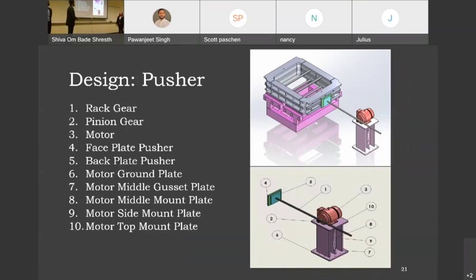For the overall design, it's currently a skeleton design right now because it will need an inverter and an enclosure for the motor, to protect against the residuals in the air, and the overall system will need an enclosure as well. Generally, it will be a rack and pinion system that has face plates attached to the drag, and a motor at 5.5 HP minimum. We chose 7.5 HP. The mount for the motor is a base plate.